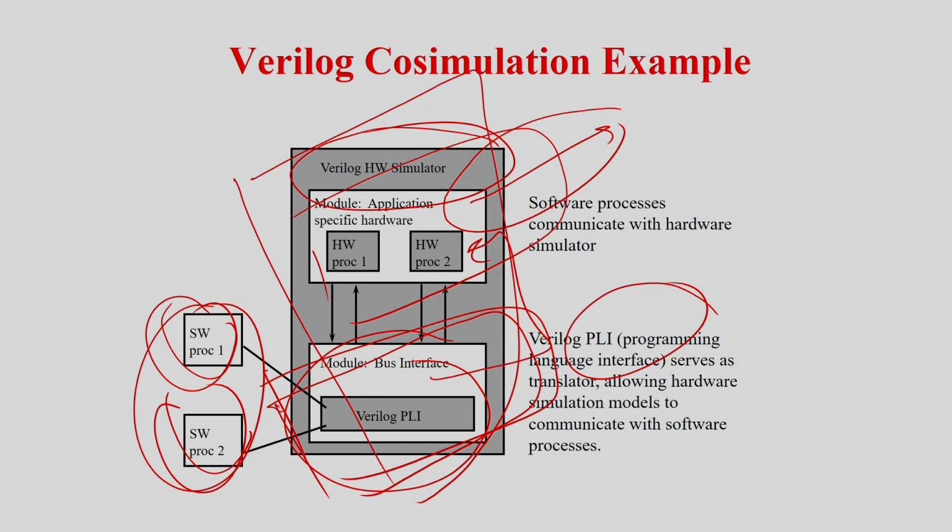So again, such an environment can be developed, and there are a lot of web environments there, but the main problem is the speed. You can think this has become very complex. Hardware is generally maybe 100 lines of Verilog code. Now if you are trying to integrate with C, the C language will be translated or mapped into a corresponding Verilog language so that it can interface with the hardware written in Verilog, that is the pure hardware.